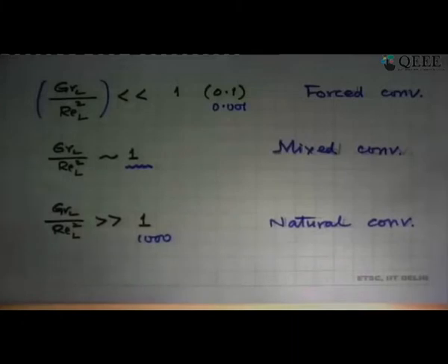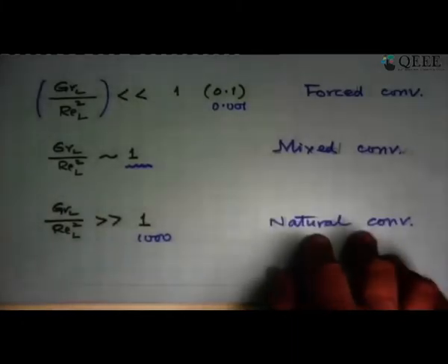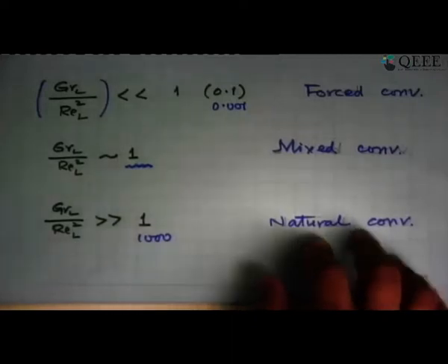What we still need to do is, what are the other configurations in natural flow, because we have only looked at one case: a vertical plate in still air, heated or cooled, both cases the solution is going to be the same. Let's look a little bit at the dynamics of the boundary layer that is developed on the plate, and then we will go to other configurations.